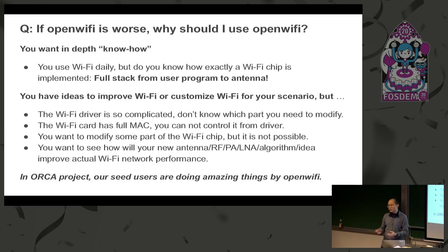And if you are using some full MAC Wi-Fi chip, not the soft MAC, which means that the Wi-Fi chip is very complicated, with all the MAC layer, link adaptation, everything, advanced control in the chip, in that case you don't have full control of the chip from the driver. Maybe if you want some special functionality, you need to reverse engineer the firmware in the chip a little bit, right?